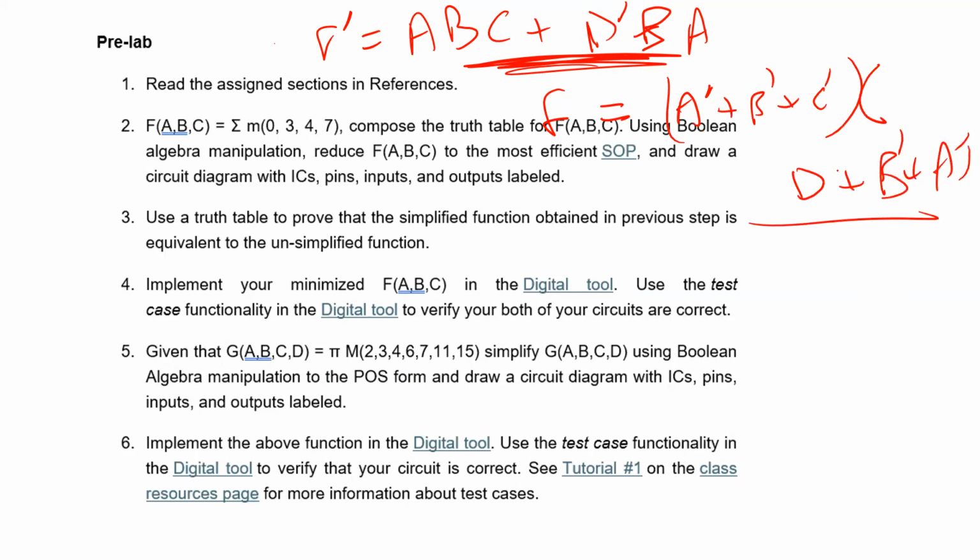As I said in the lecture, this or is converted to and. Also, when you calculate De Morgan for this one, every variable is going to be complemented. You have to complement every one, and any and here you have to make it or. So this is how you can do it.